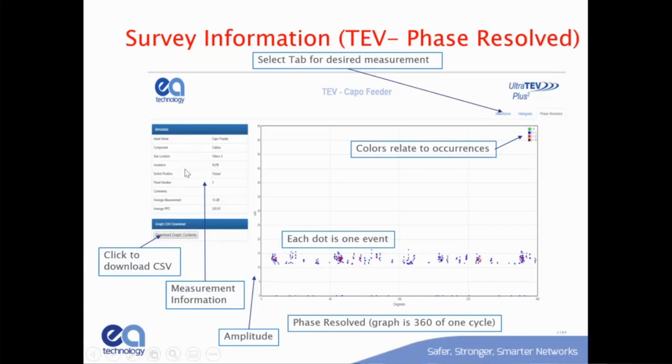Now, all this equipment, all this data that you loaded in here, that can be preloaded into the instrument as a workflow. And the last feature I haven't talked about is the instrument itself has a reader for NFC tags. So these are little adhesive tags. You get them printed up and say ABM on them, and you stick one on each piece of gear that you test. The first time you do a survey, you go through and you write the panel number to that tag, and it's got a memory chip in there, and it'll store that forever. Next time you come and do the test, you just hold the instrument up to that, and it'll say, okay, I'm at panel 706. Great. And it'll let you pull up that data from the workflow without doing all this typing at every station. So it makes you faster, more efficient, less errors, and less time wasted standing in the middle of the substation.